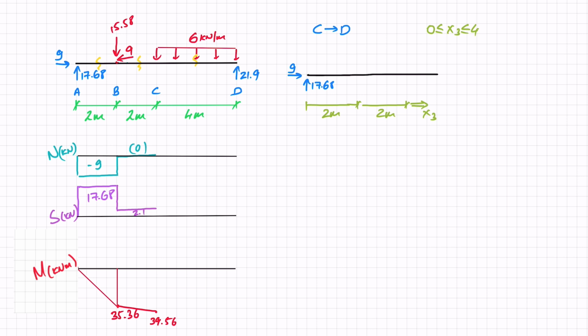I've got the two components from my load, which were 9 and 15.58. And I've also got this UDL starting up. Additionally, I've got all my internal forces exposed, so N x3, S x3, and the bending moment M x3.